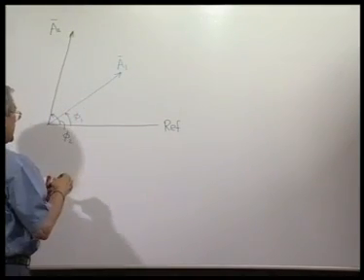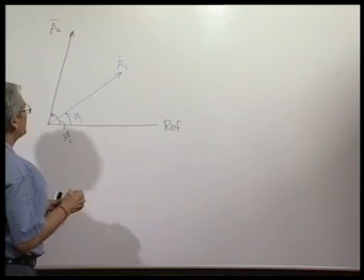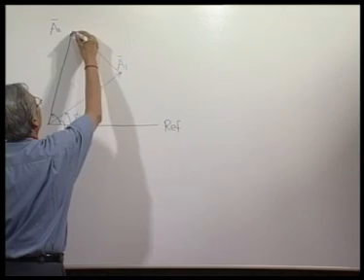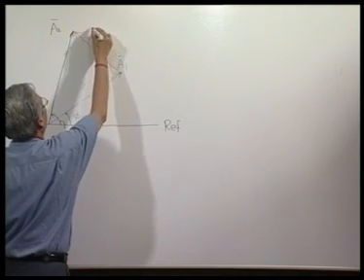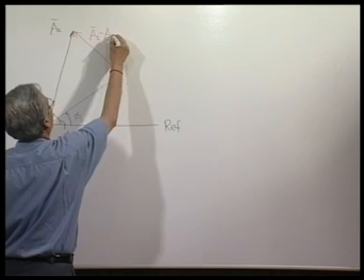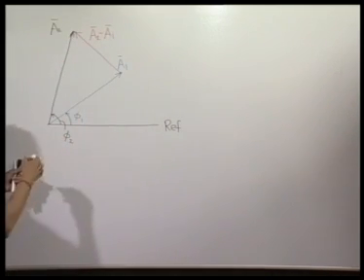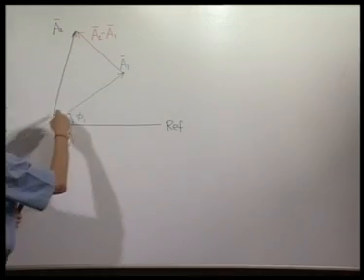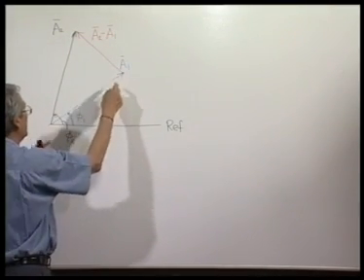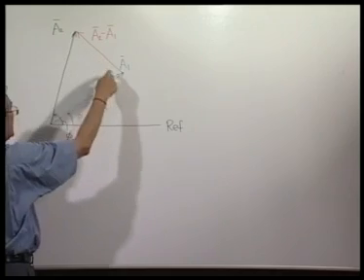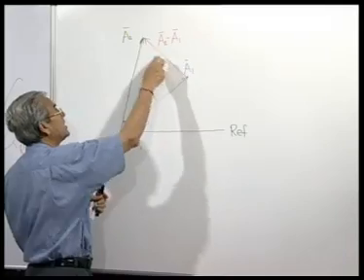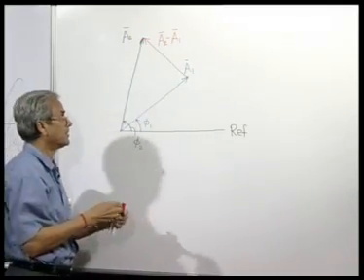Now, what is this quantity? I am representing this bar over the number to indicate that they are vector quantities. Now, this is A 2 minus A 1. Originally, without any trial mass we had this vibration, with trial mass we have this vibration. So, the original vibration plus this becomes the final. So, this is nothing but the effect of the trial mass.